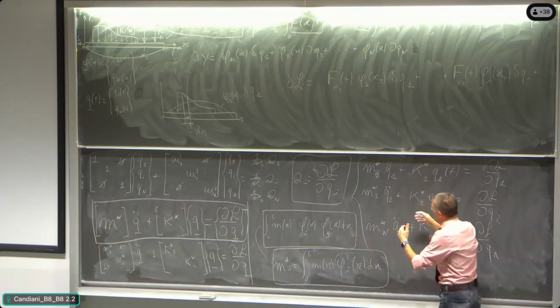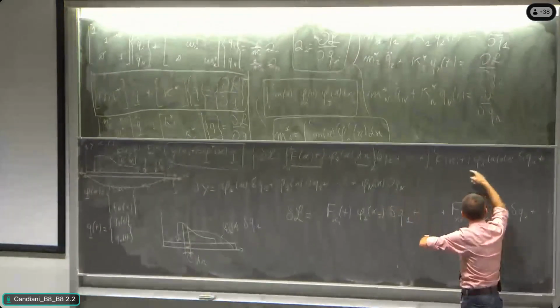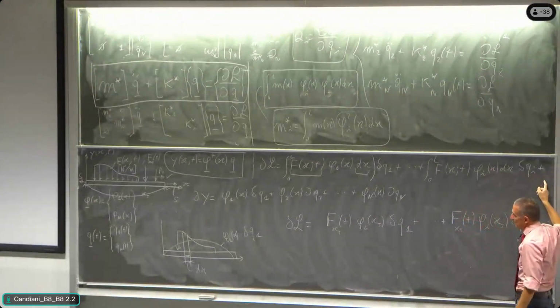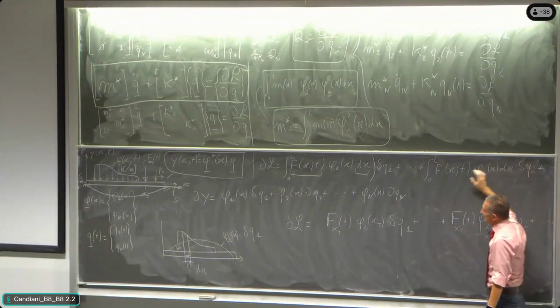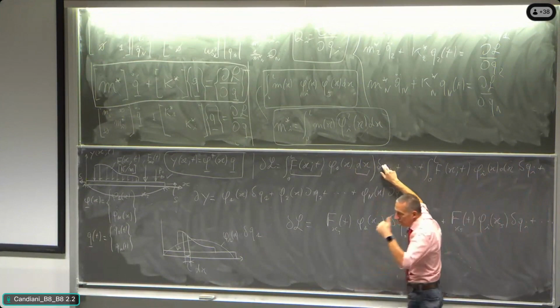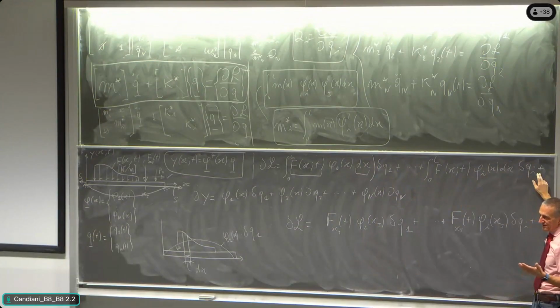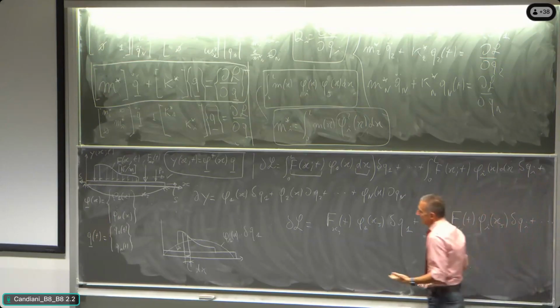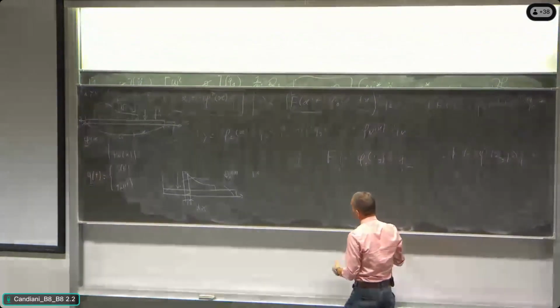So if I have to write the partial derivative of the total virtual work, that is working with all the possible variations of the coordinates, with respect to the i-th coordinate, what do I have to do? I have to say that all the variations are null, delta q1 is null, delta q2 is null, all of them are null, but not delta qi. Partial derivative means exactly this. It means that you have to put 0 everywhere, but not delta qi, and you have to divide by delta qi.